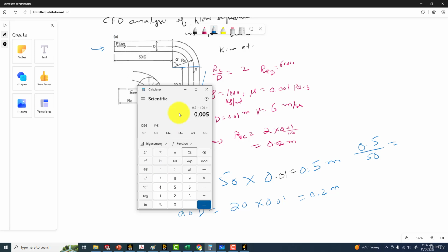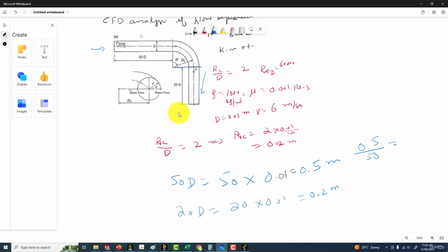From my analysis, I found that 0.002 would be the best one. So 0.002 is going to be the global size, the element size in the whole model. So what is the meaning of the global size? Global size means that if you don't specify any sizing on any part, this size will take place. Any unspecified sizing on any surface, this size will be used by Ansys meshing.